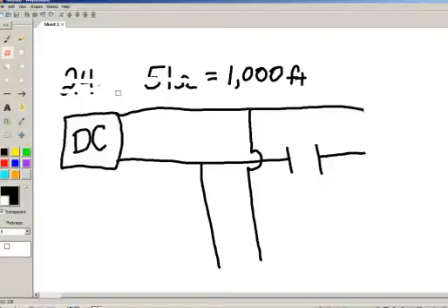Now, when I refer to kick on an analog meter, for those of you that still have an analog meter, there's a bunch of them out in the field. There's usually a switch associated with the meter. There was on mine anyhow. And that switch was labeled REV. Now, I didn't know what that meant. All I knew is that that is the switch that I would toggle back and forth to get the needle to deflect or move, right? And based on its deflection, I could calculate in my head about how far that was distance-wise.